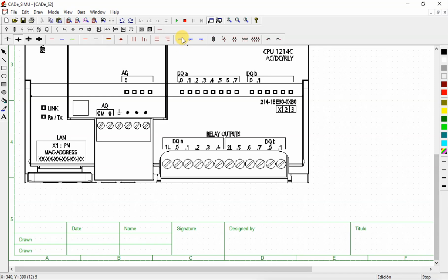Now for the output, you can use the same power supply from what we had above, no problem, but to be a little bit neat, let me have here an independent power supply. It's on. So I'm going to connect this neutral. Since this is a relay, I hope you know how relays work. Here is the relay, I'm going to put the common here. Then I'm going to have my lamp. I'm just going to have here a simple lamp.